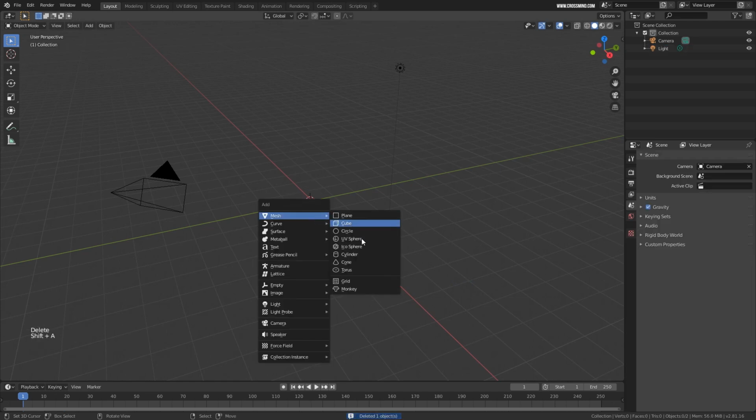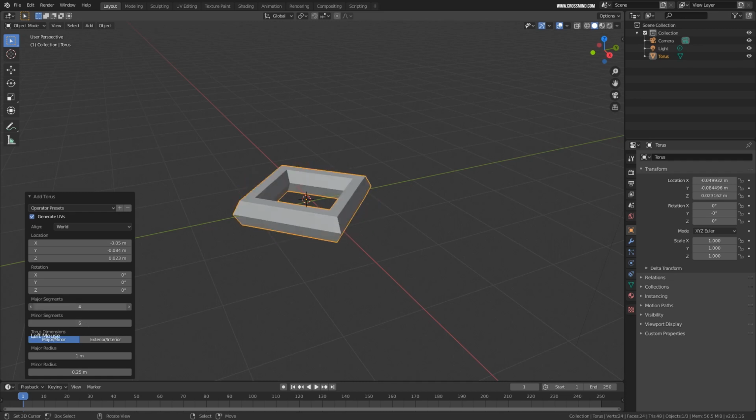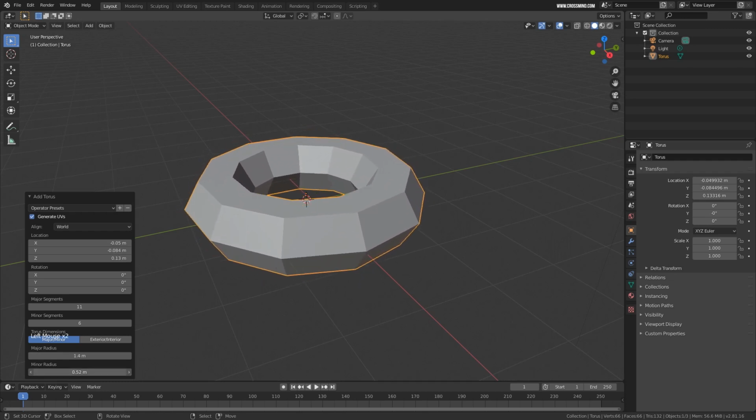Okay, so let's say you create a torus, you can zoom in and zoom out, that is okay. So now I just want to set up the segments, like how many points I want in the surface. Okay, if I want very low resolution, high resolution, or I want it to look like a four-sided torus. Transformation, you can always do that later, but to set up the segments and all, this is very useful. Okay, and you can also control parameters like radius and stuff.